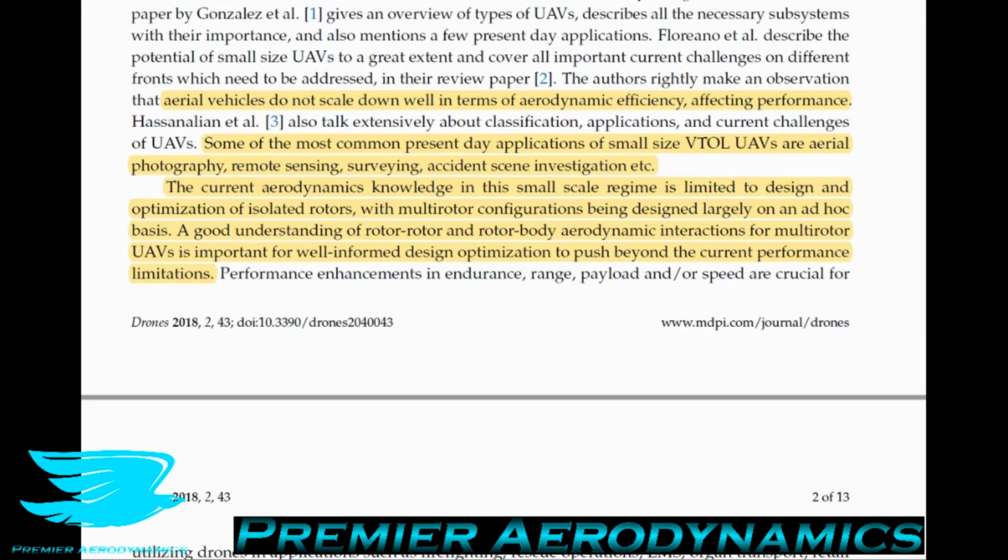So what that means is they investigate just one rotor and they look at what the aerodynamics of that is. And then they assume that if you just put all these rotors together, they're still going to perform in the same way, even though they may interact with each other in real life. But that's why there needs to be more research to see how putting 2 rotors together or more affect each other's performances, because they could be like stealing each other's air a little bit or washing some of the wake into each other's wakes, which then affects their thrust performance, and they also have potentially an upstream effect from there.